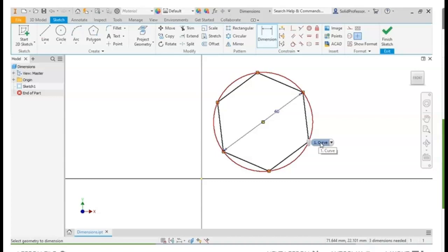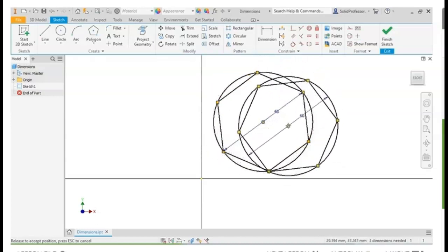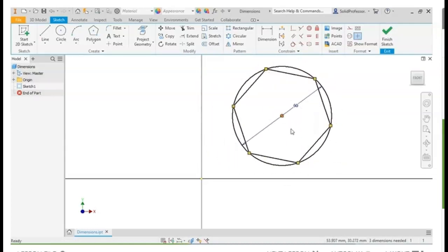With the shape size now defined, the status bar now reports that 3 dimensions are needed in order to fully constrain this sketch. Remember how a moment ago I was able to change the sketch's size and location by dragging around the sketch? If I try and drag the sketch now, notice that only the location changes. This is because the diameter dimension is now driving the geometry, meaning that it is a parameter for the model. This relationship between dimensions and geometry is the basis of parametric modeling and means that if I want to change the sketch's size in any way, I'd need to edit this parameter.